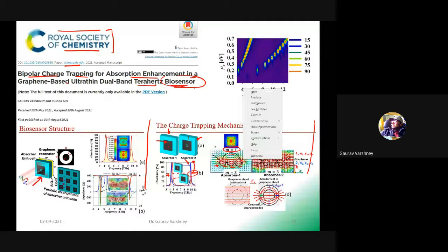So this was the reason behind getting the 50% absorption in the upper band at the frequency of the higher order mode. But at a similar frequency, if we place some annular geometry, what will happen? This will provide a capacitive effect, and this will trap the charge along the direction of the electric field vector.